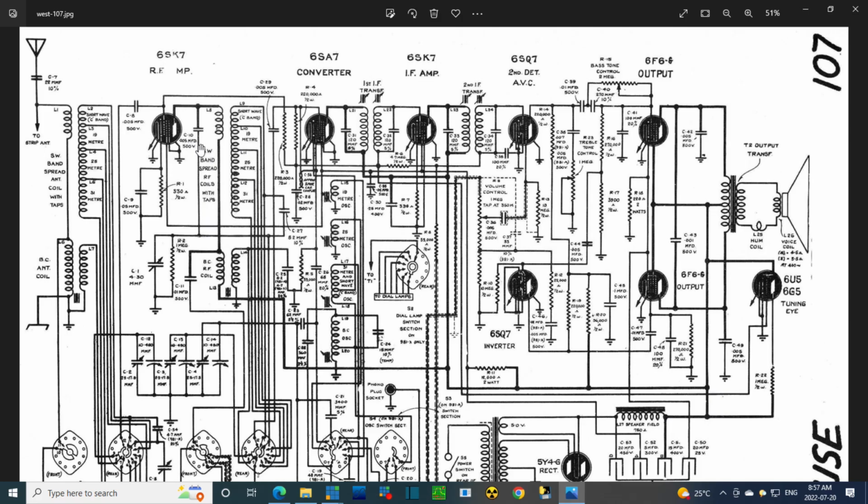And what's it doing? I'd have to get my book out and read this to be absolutely sure. It's right on the plate circuit. Probably has something to do with oscillations, unwanted oscillations, or something like that. I'm not entirely sure. Not a tiny capacitor. It's not a big one either. For sure, if it's shorted out, which it was doing, it's got B plus and this power supply behind it to push current through it and cause sparking at the high voltage. So there's no question that.